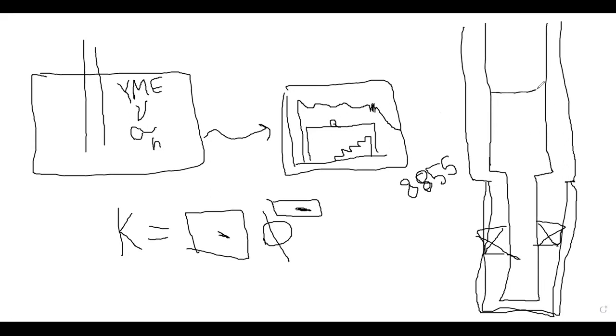Simply, we will define the 4.5 P110 tubing and 3.5 P110 tubing. From the completion engineer, 4.5 P110 has an ID of 3.86 and 3.5 P110 has an ID of 2.75 inch.